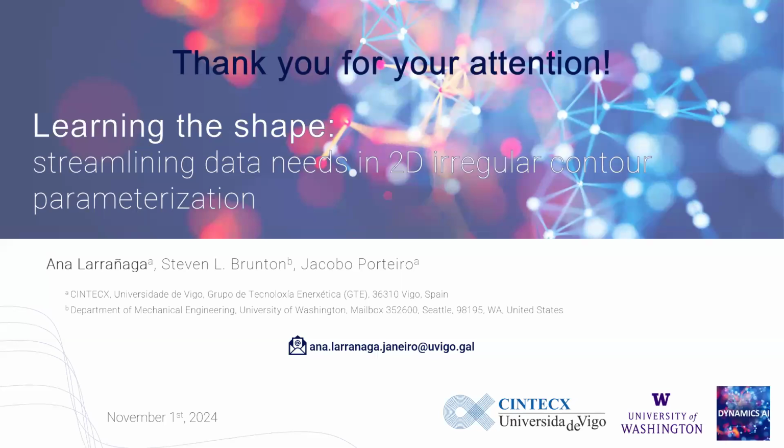So don't run thousands of simulations without looking at them. It's better to run smaller quantities, train a model, and then compare. There's going to be one point where you don't really see an improvement. That's where I would say stop. But this is very context dependent. It depends on the problem. The percentages I was mentioning were for this microfin case, but other cases might be more difficult to determine.